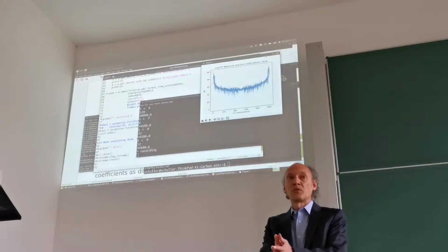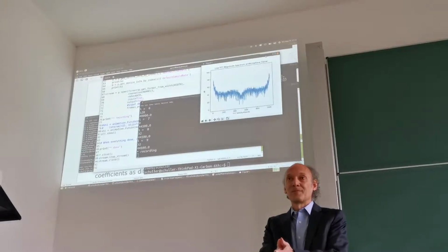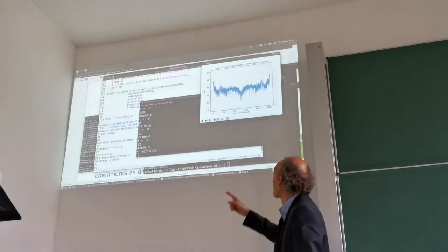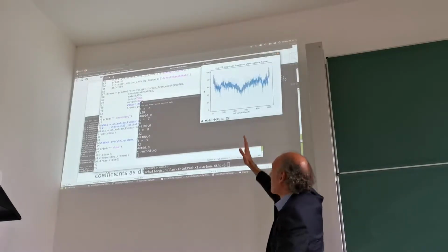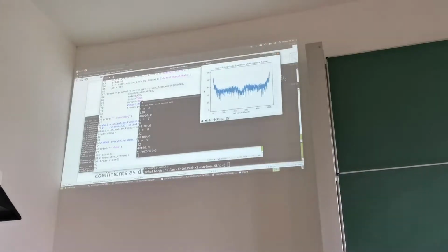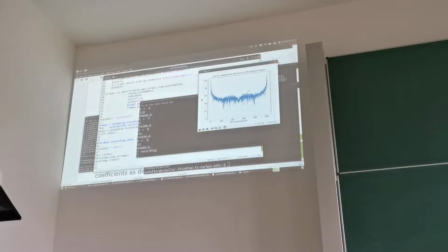This is the maximum frequency that we can represent with the sampling grid. So you can nicely see the symmetry around the center. So here's the center, and it's always symmetric around the center. So basically, when we go to the upper limit here, 1024 would be identical to DC again. And that's also why we are not computing it.